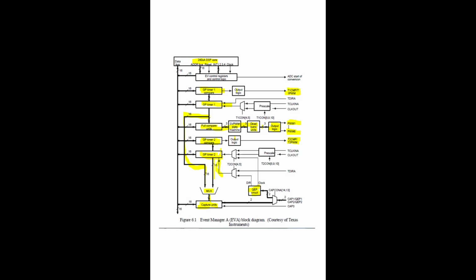The timer counts every pulse, and that count is given as a signal to the DSP controller, which already has some set speed. The timer counts according to how many pulses came from the quadrature encoder pulse circuit. That count is given as a speed signal for the DSP processor. So again, that will be used to control the speed of the motor. And these portions that we have seen are used to control the speed.